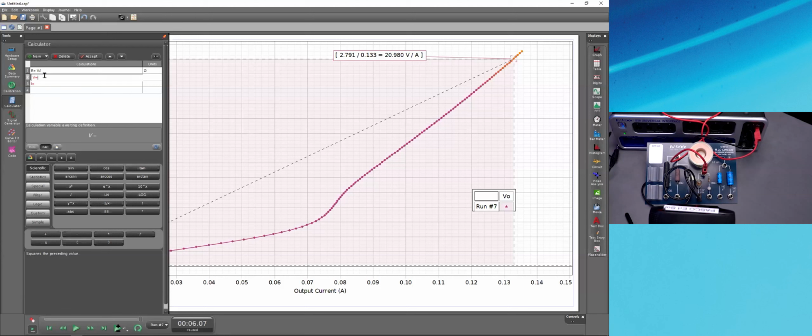Well, the voltage is not a single value. It is all the measurements coming from the voltage sensor. So I need to be able to define an entire array of data. The way I do that is to come down to the data selector button, where I can see that I can choose different measurements. I'll choose output voltage for voltage in volts. And for current, I'll go back to the data selector and insert the output current in amps.